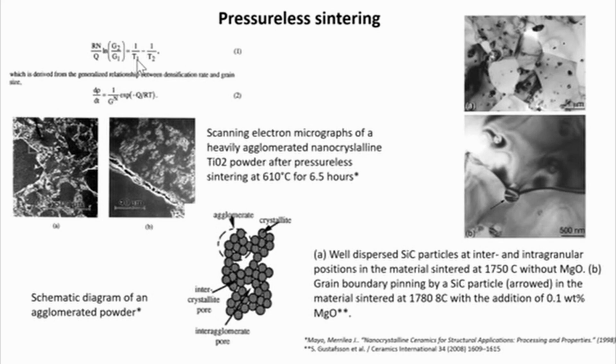In practice, such easy sintering of nanoceramic powders is rarely achieved. More commonly, the nanocrystalline powder begins to sinter at quite low temperatures, but full density is not reached until much higher temperatures or longer times, with the result that the grains grow well beyond their intended nanometric size. As an example, you could observe the microstructure of sintered nanocrystalline titania powder with a starting grain